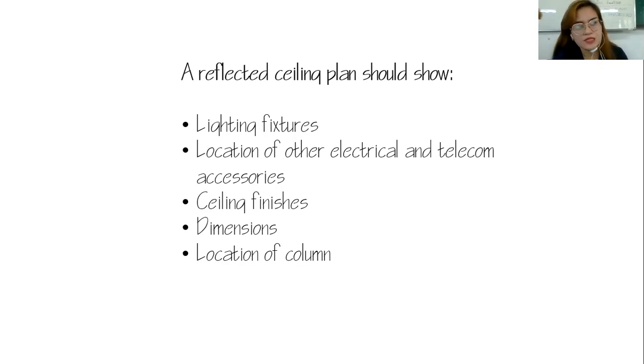And also, it's important to show the elevation markers on your reflected ceiling plans. Basically, if you're going to have a cove lighting, there are certain changes of the elevations, right? If there's a certain depressed area, you need to indicate it.